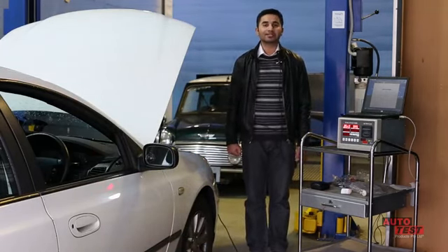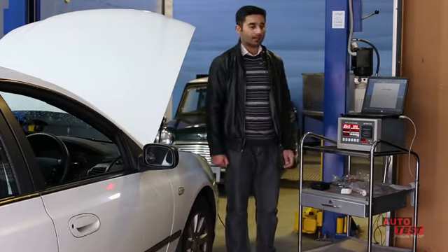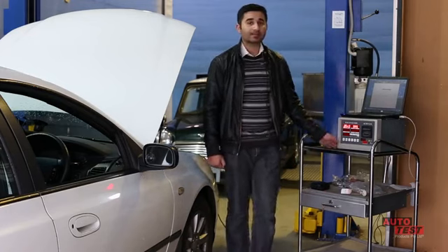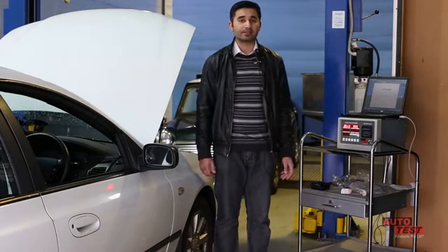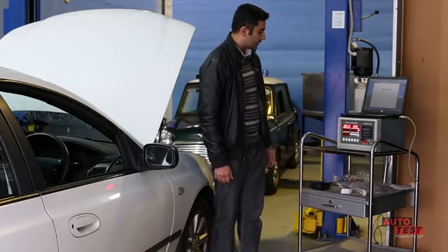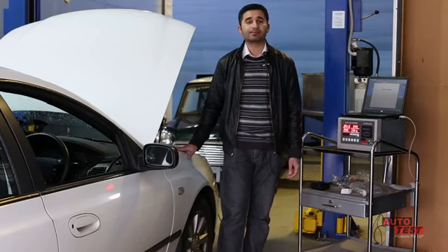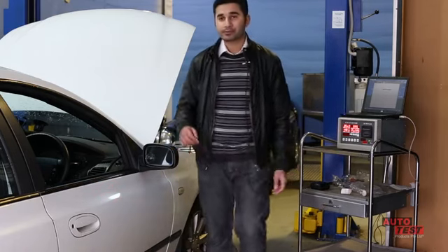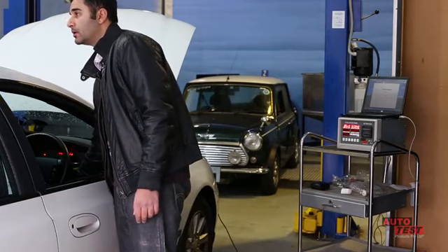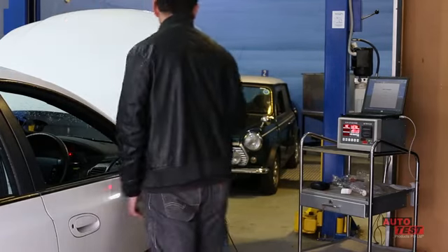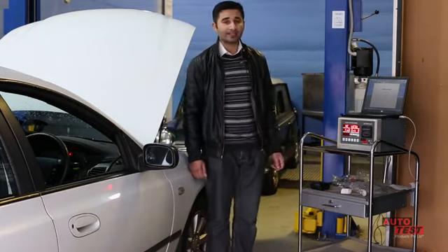Okay, both the gas analyzer and the smoke meter have been warmed up. After the warm-up, this gas analyzer is going to go through a zeroing and HC test, which is currently performing. We'll wait while this is happening. In the meantime, the car has been warmed up as well. We're going to start the car for now. Okay, we'll wait until the HC test has finished.